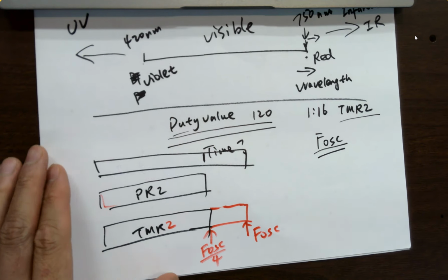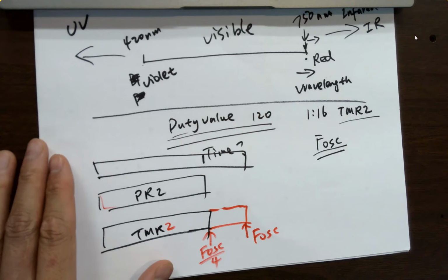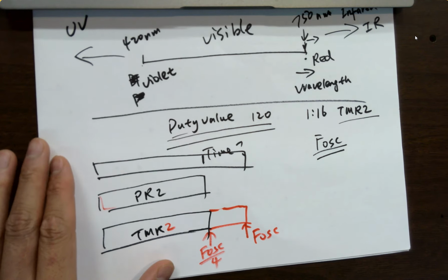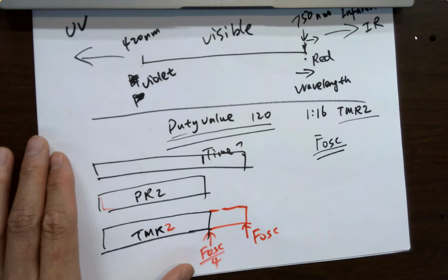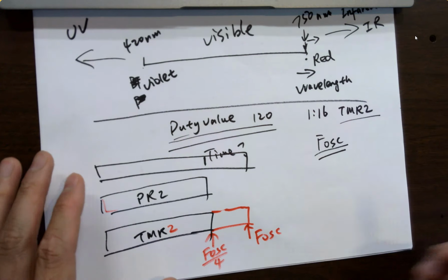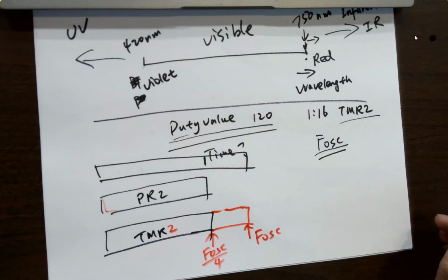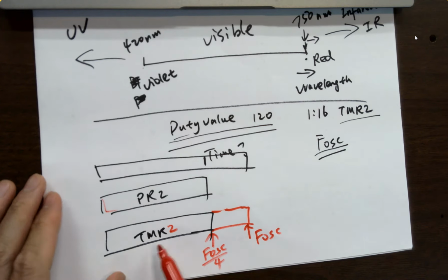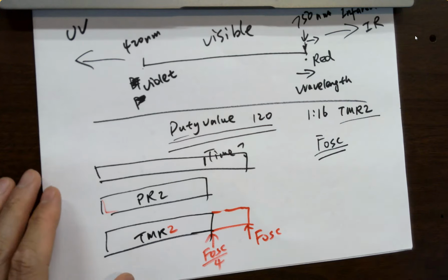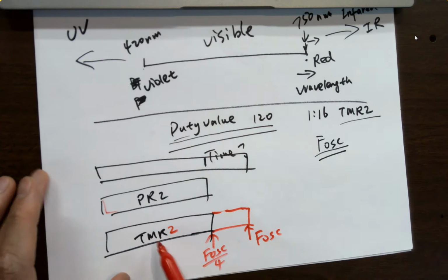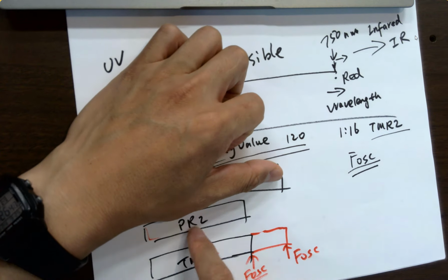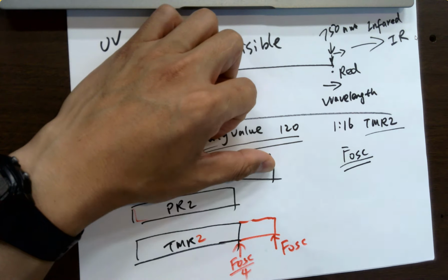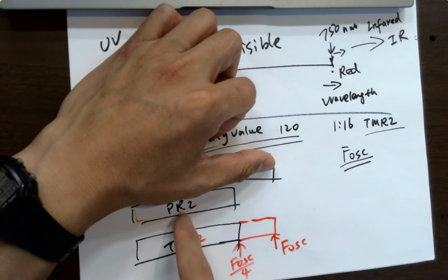So we use PR2 when we're using Timer 2 like a normal timer, where we're writing regular values to it, but we use those other 2 when we're doing PWM. The other 2 registers that you talked about last class that are also 10 bits, the high and low. Do we only use those when we're doing PWM? You can use Timer 2 for other purposes, but we are not. Definitely you can use Timer 2 to count for other purposes, right? But the way Timer 2 works is it's always matching with this one to turn on the flag. That's how that works. Even during PWM? PWM, of course, that's what we do here.